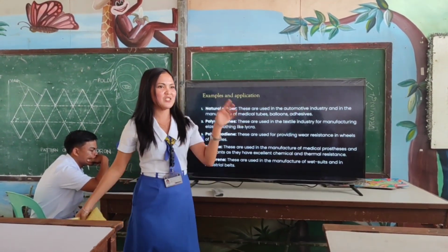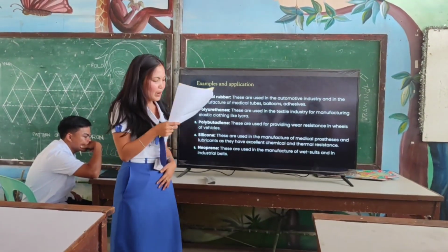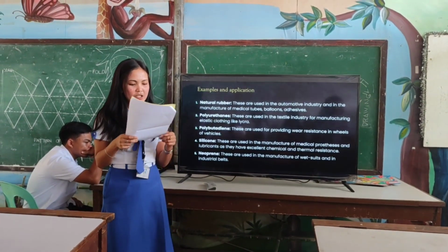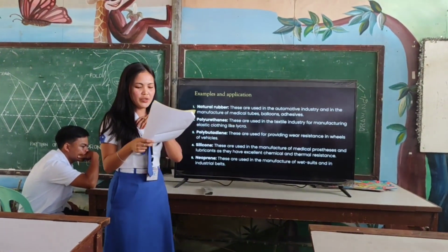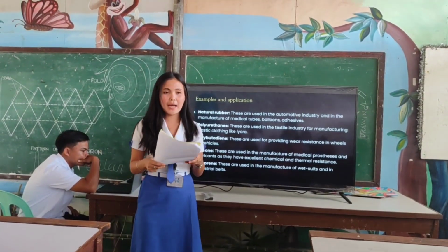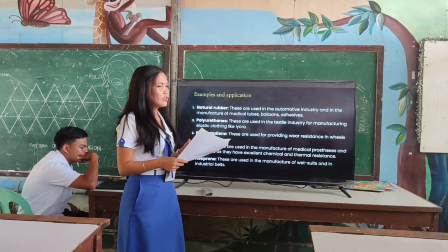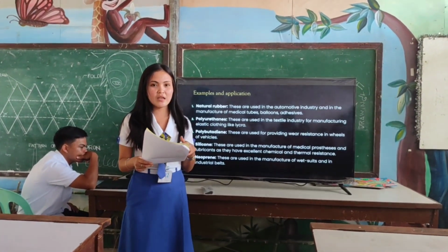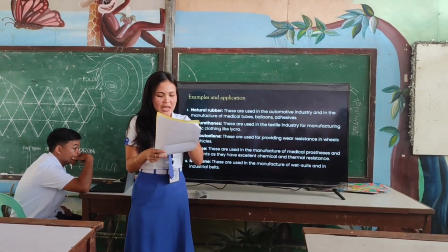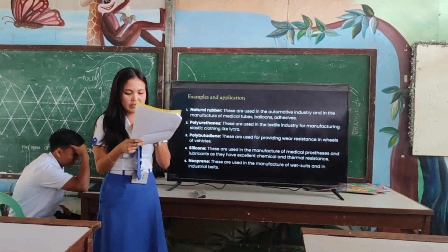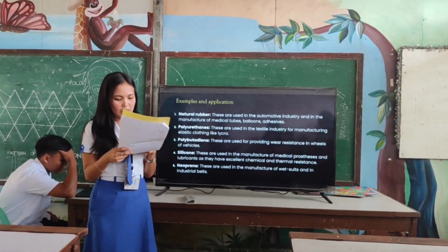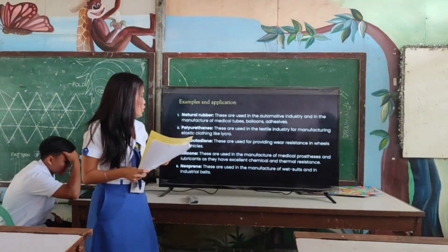Polyurethane, abbreviated as PU, is a broad term that encompasses a large group of polymers known for their versatility and resilience. There are two major types of polyurethane, which are the foam and the solid. Polyurethane has excellent abrasion resistance, and also has decent resistance to being attacked by oil, petrol, and many common solvents.